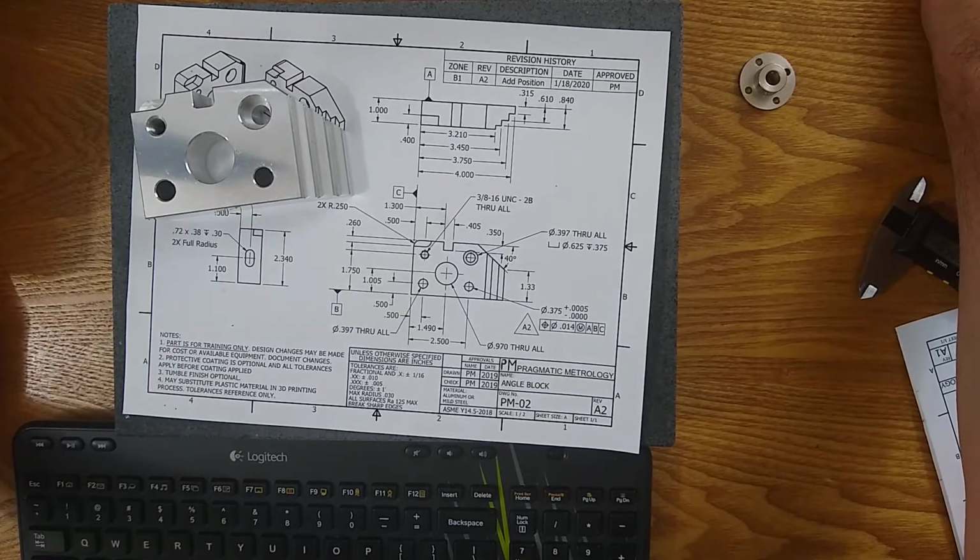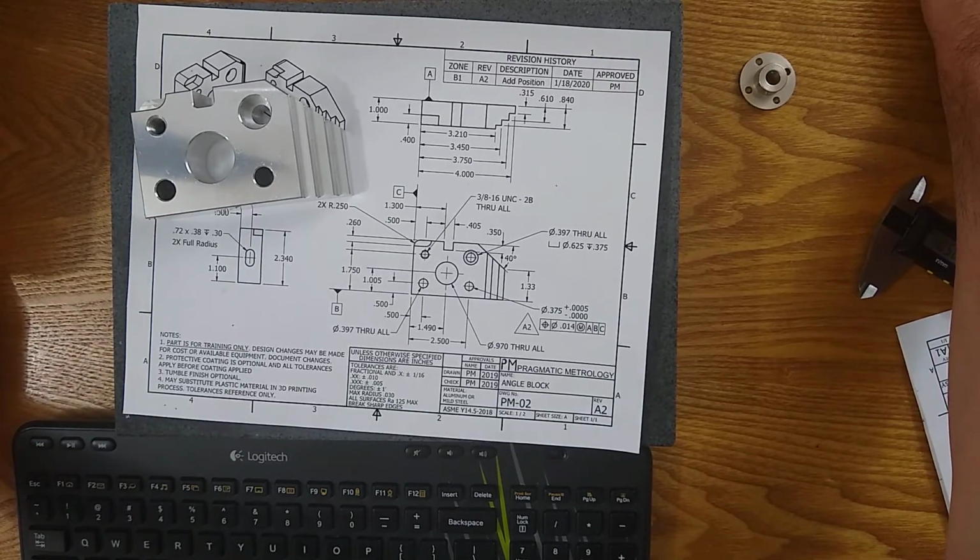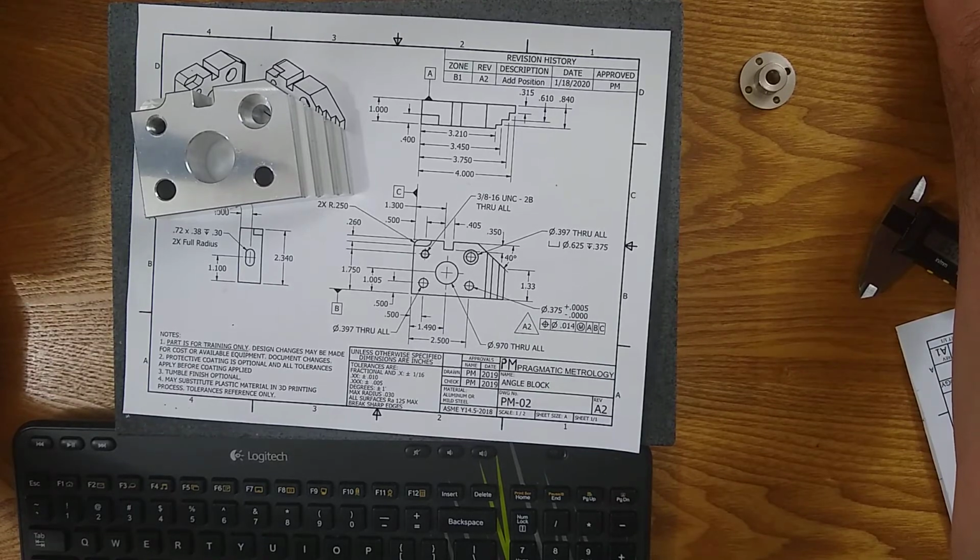This vertical red line represents the low, and that is a 0.966 diameter. This horizontal red line represents the high. It's the same circle, but it's elliptical shaped. And so it is 0.974, but my average is 0.970, right? So 4 thousandths below, 4 thousandths above, the average becomes almost perfect. So if you're not looking closely, it could be you used your calipers.